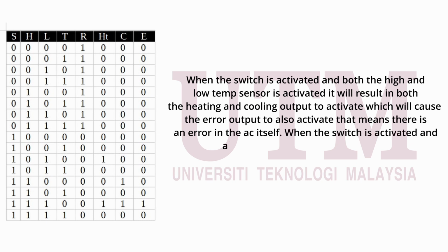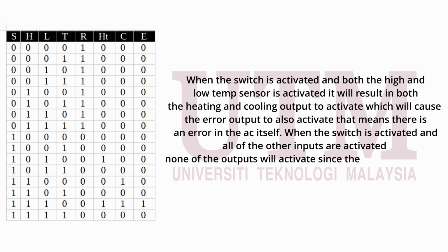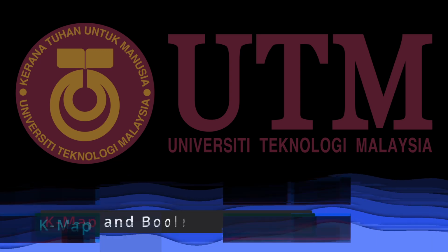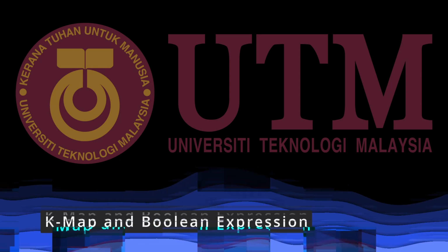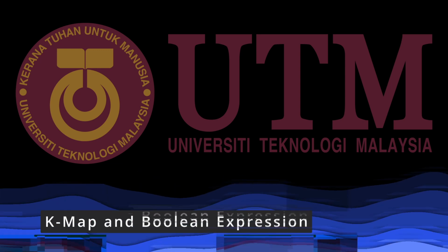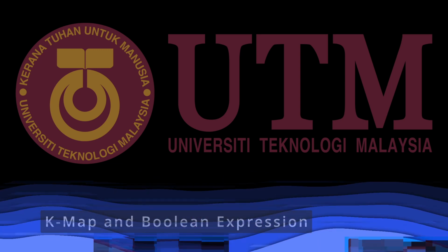When the switch is activated and all of the other inputs are activated, none of the outputs will activate since the threshold input is activated, so the temperature is within the threshold. Next step, in the K-map, we have to use the inputs and outputs from the truth table we made to make the K-map for the 4 outputs.